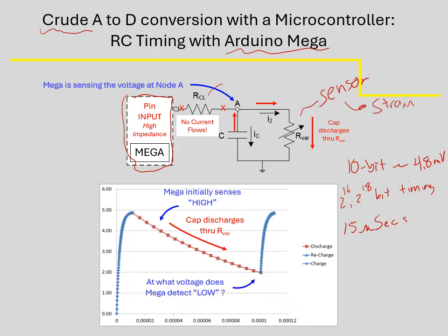It changes resistance as a function of the force applied to it. A photoresistor changes resistance as a function of the amount of light falling on it. We're going to use photoresistors in the final project, and you've used some already in the lab. This could be a photoresistor, and you hook up this circuit.